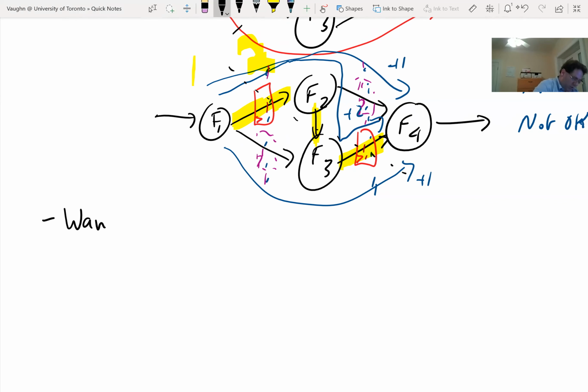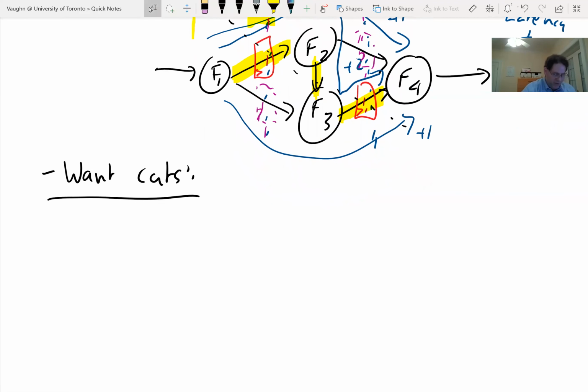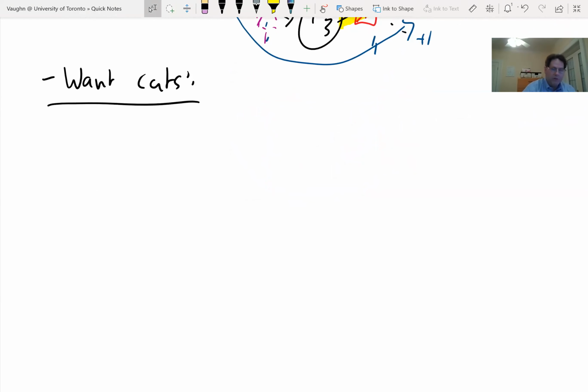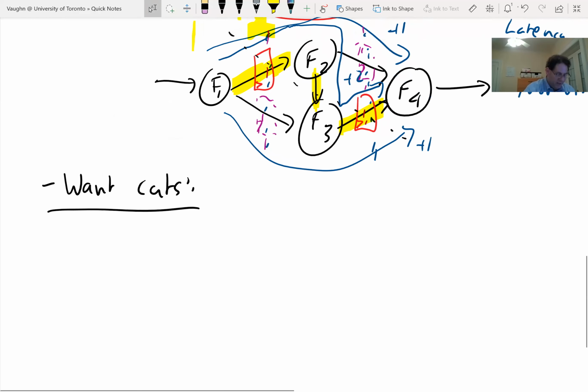Okay, so let's talk about what we want in the cuts. We needed legality in pipelining, so we have to balance all the latencies of the paths. We have to add the same amount to all of them, which we can turn, for this important subclass of feed-forward circuits, into a cut test. We have to pay attention to the direction we're crossing the cut in. What do we want in the cuts? I showed you here we could make lots of different cuts even in a little circuit. If I'm choosing between a few different cuts, which ones are going to be more desirable than others? And I can let you keep looking at this one.